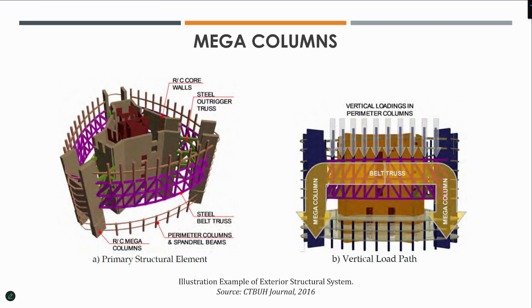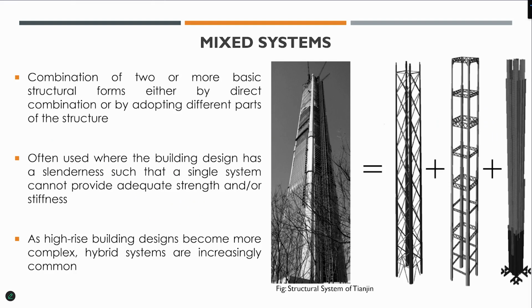So there's a gap. This is very important because these columns are very small, and they must transfer the load to the main columns. One of the commandments, all gravity load must go to the columns which are taking the lateral load. So we don't want these columns to take any load. So every few floors, 10, 15 floors, you transfer them, then start again. So that's the belt truss. Every belt truss is also a transfer girder. So it's doing 2 things. It's transferring the forces of the column above and also acting as a belt truss. Like I said, people just combine things everywhere. So that's another example of the same building.